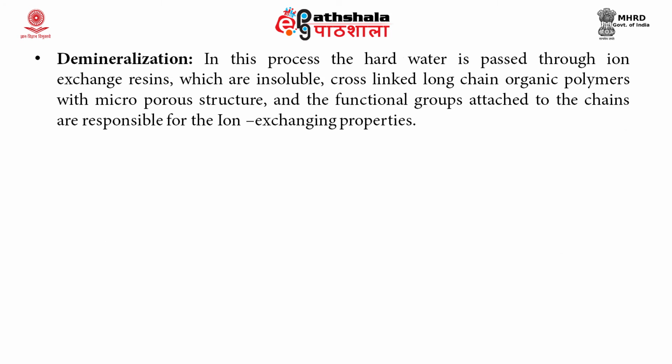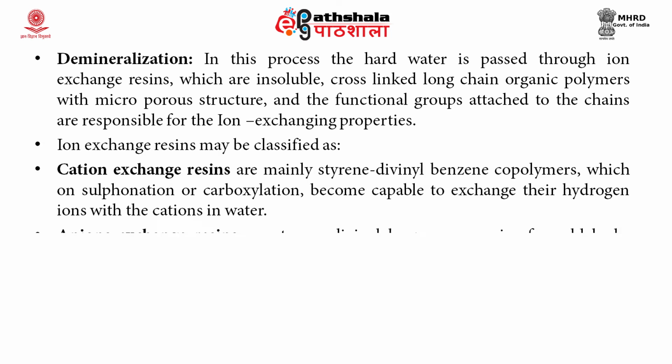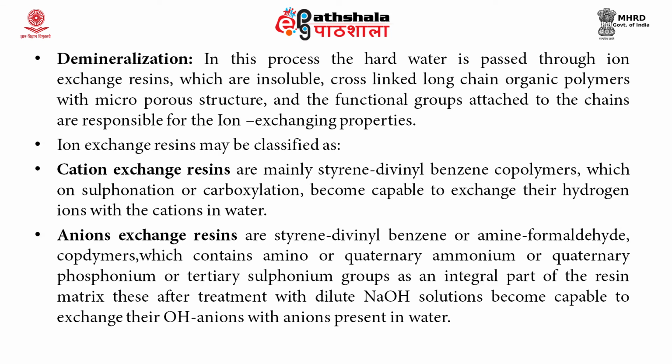The second category is demineralization. In this process, the hard water is passed through ion exchange resins, which are insoluble, cross-linked, long-chain organic polymers with a microporous structure, and the functional groups attached to the chains are responsible for the ion exchange properties. Ion exchange resins can be classified as either cation exchange resins or anion exchange resins.